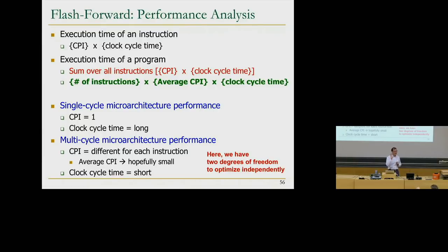Okay, so now you know the basics of performance analysis, yes? Would that mean that I chop up an instruction to multiple parts and then execute them over multiple clock cycles? Exactly, yeah. Wouldn't they create overhead because I have to store intermediate results? Exactly, yes. That's the overhead that we will also see. So basically, your colleague pointed out that there's an overhead, yes, because you need to store the intermediate results. And based on the timing and verification lecture, you know that whenever you need to store something into a flip-flop, there's additional delays. And also there's overhead in terms of additional area because you need to have flip-flops to store these intermediate results. So it's going to be more expensive to build this multi-cycle machine, but it's going to be faster. And you will see that after multi-cycle comes pipelining, it's going to be even more expensive to do the pipelining.